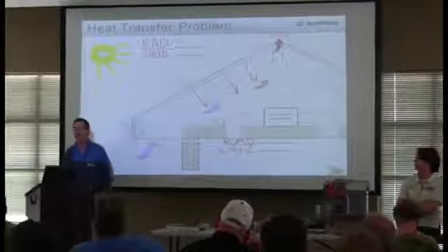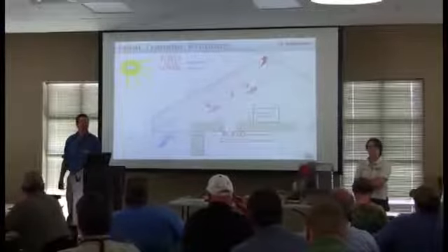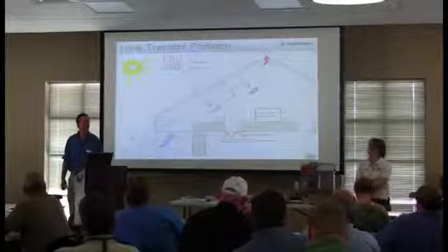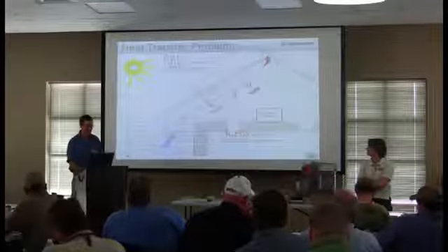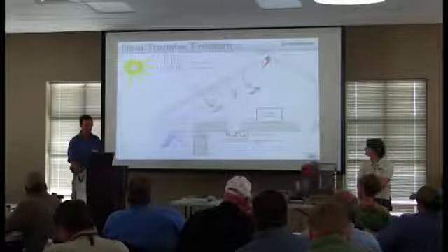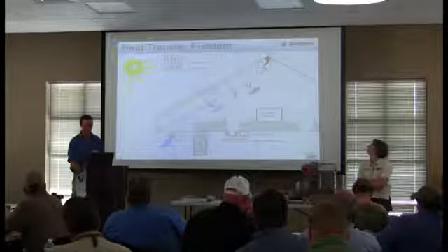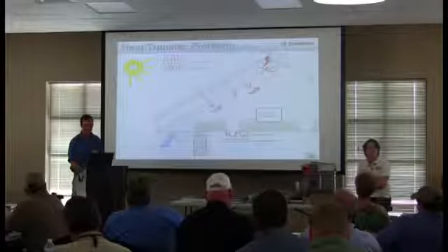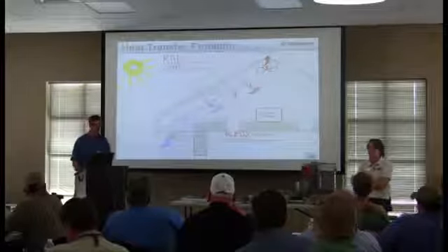And also, when you vent with air and you live in Georgia, what are you letting in? Besides heat, what are you letting in? You're letting in a lot of humidity, generally moisture, heat and hot, that's right. So the one thing that we don't want you to do is, I'll try to draw it up here, it won't be pretty, but we don't want you to put a thing with a propeller, a bow tie up here. Power ventilator. An attic fan.